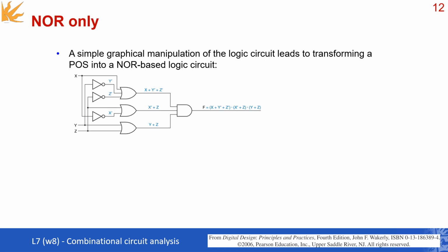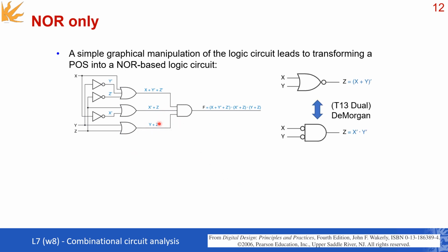And of course, we can use the same logic approach to proving that you can rewrite everything using only NOR gates. This time we're going to use the product of sums. So this is an example of product of sums. Again, by using De Morgan, a NOR gate is equivalent to this symbol over here that uses an AND gate with all of its inputs negated. So essentially this is again another symbol for the NOR gate.